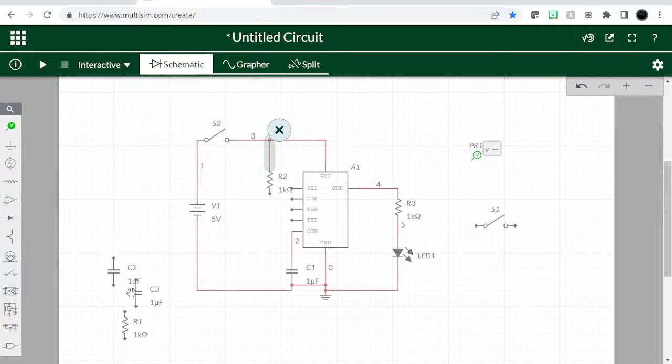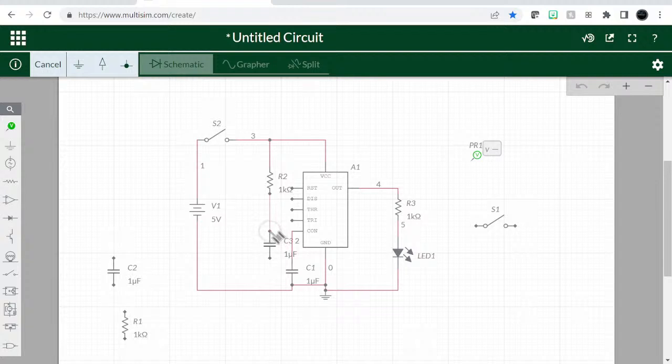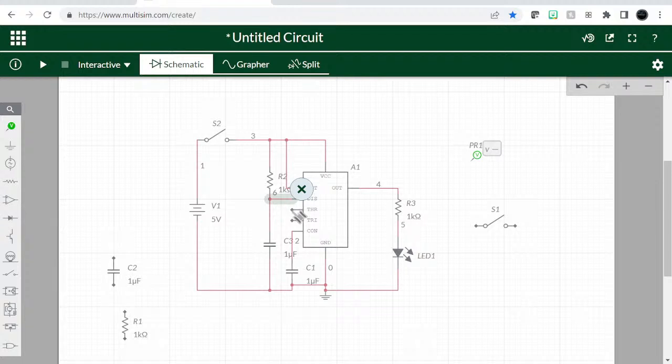And this resistor needs a capacitor. Okay, and that goes between pin 6 and 7. A reset, let's just pull our reset up. We can pull it up through a resistor just directly. We need 6 and 7. And then our trigger is just going to be separate. So we're going to have another resistor capacitor going to the trigger.